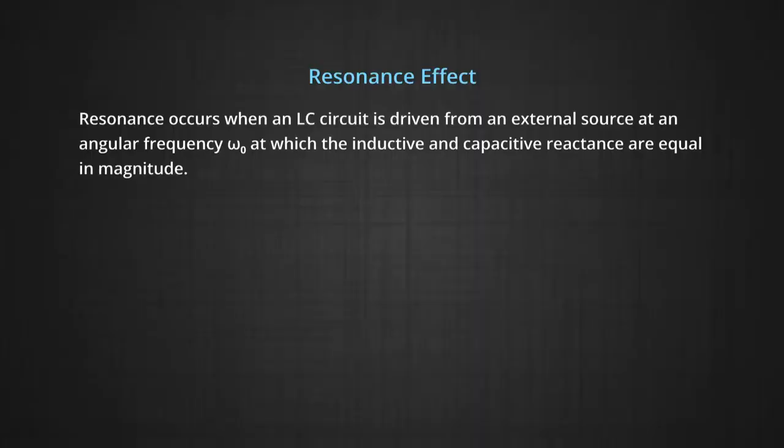The tuned circuit's action, known as a harmonic oscillator, is similar to a pendulum swinging back and forth. The natural frequency, that is the frequency at which it will oscillate when isolated from any other system as described above, is determined by the capacitance and inductance. In tuned circuit electronic equipment, the oscillations are very fast, that is thousands to billions of times per second. Now, here we will discuss the resonance effect.